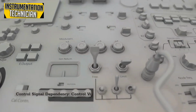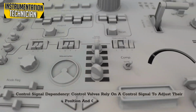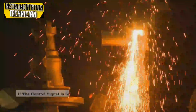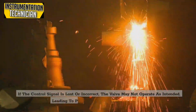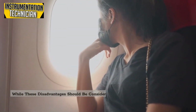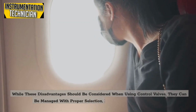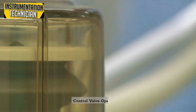Control signal dependency. Control valves rely on a control signal to adjust their position and control flow rates. If the control signal is lost or incorrect, the valve may not operate as intended, leading to process issues or safety concerns. While these disadvantages should be considered when using control valves, they can be managed with proper selection, installation, and maintenance.